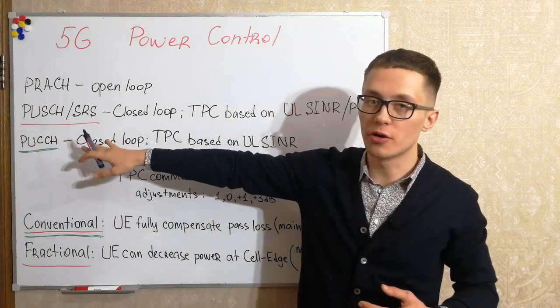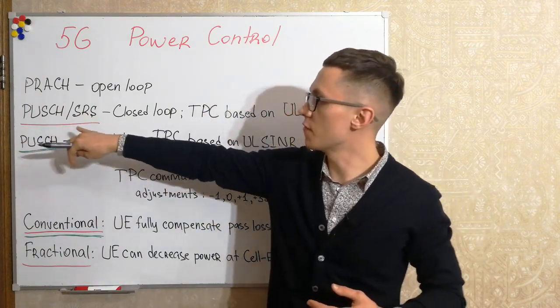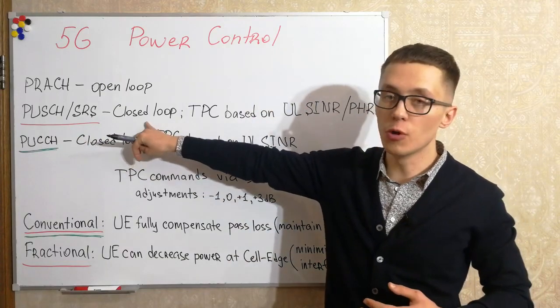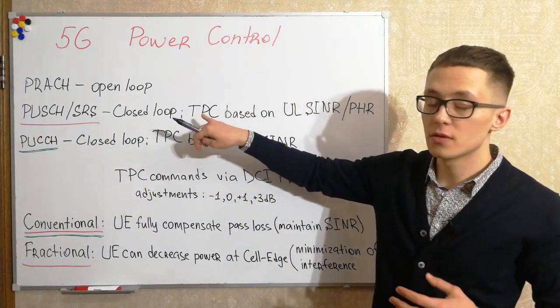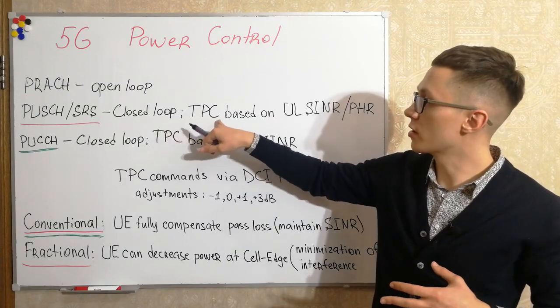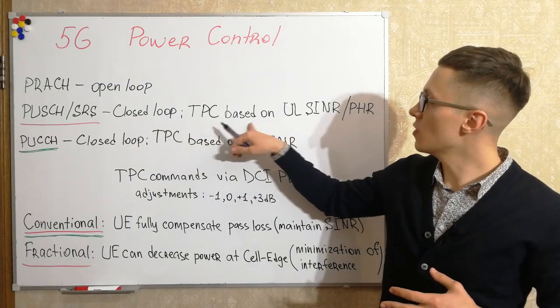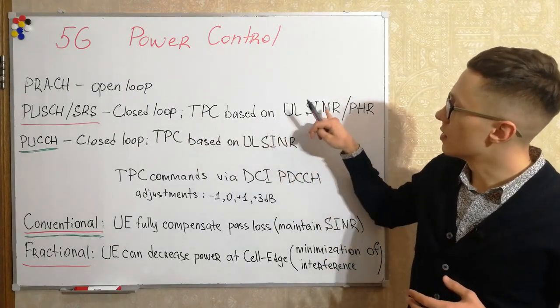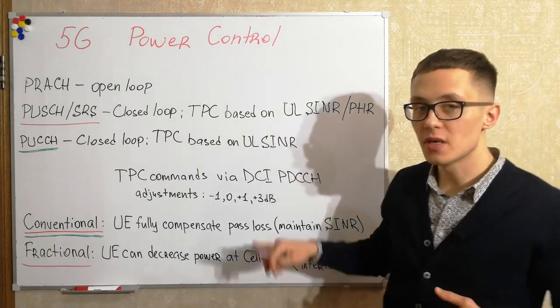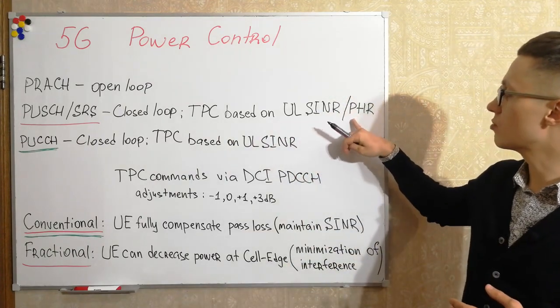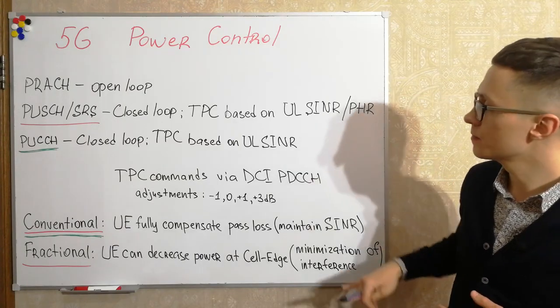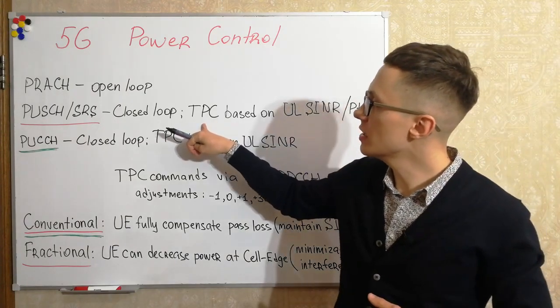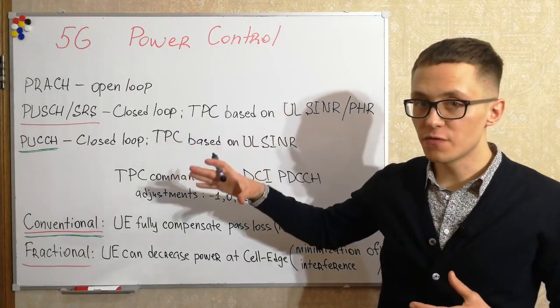PUSCH, uplink shared channel, and sounding reference signal use closed loop techniques, and transmitted power control can be based on uplink signal to noise ratio, or it can be based on power headroom reports. Actually, there can be a difference.